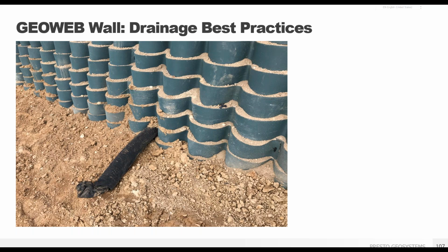It's also important to make sure that wherever the pipe drains is set up such that excessive erosion will not occur at the outfall, which would lead to undermining of the wall at that point. This is the most common type of drainage mitigation. The drainage system needs to be designed by your project engineer and can include as many pipes as necessary to ensure that water is properly collected within the wall structure.